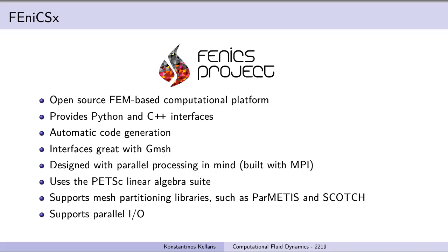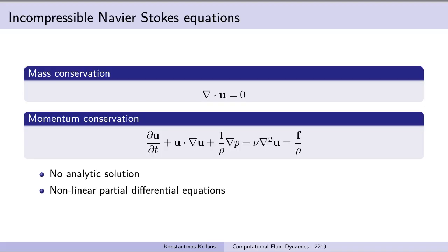It uses the PETSc linear algebra suite to solve linear systems in parallel with direct or iterative solvers, supports mesh partitioning libraries such as ParMETIS and Scotch, and supports parallel I/O. The developed software can solve the incompressible Navier-Stokes equations for both transient and steady-state problems.